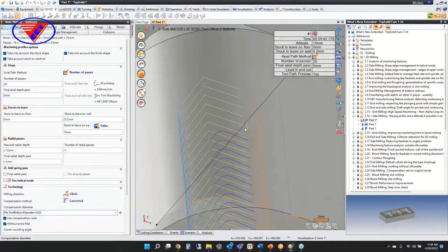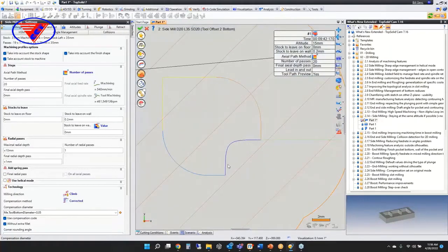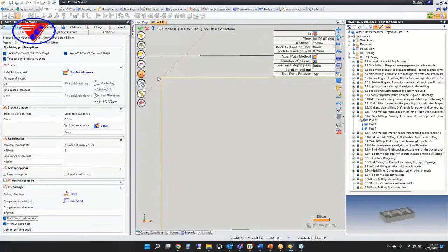Now, because of that, if we look at this straight down, you get motion like this because it needs to shift the toolpath. Okay? It's still gouge free, but you're still making kind of a hard angle move there, right? So if you don't want that, get rid of this extra movement here. But in this corner, you're going to have a sharp corner because it's a size for size tool. So the only way to not have that sharp corner, obviously, is to put a smaller tool in, right?